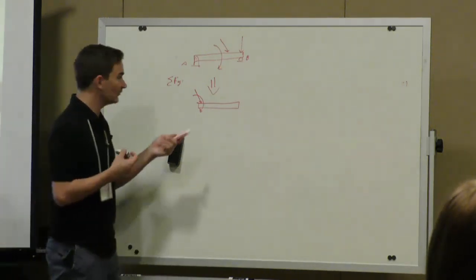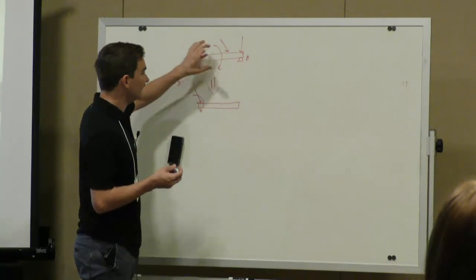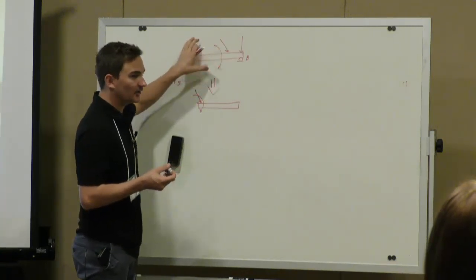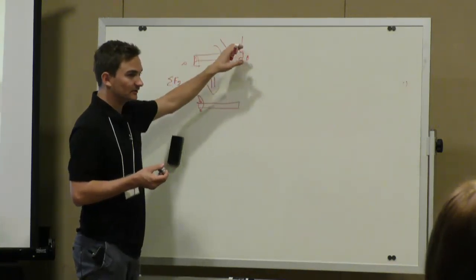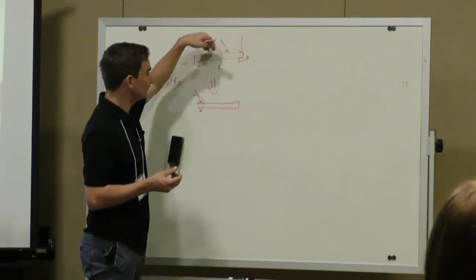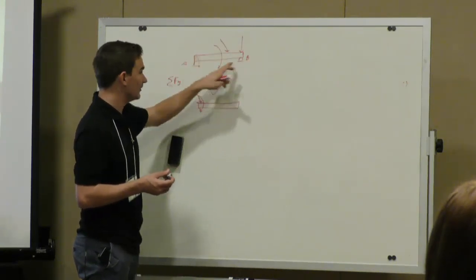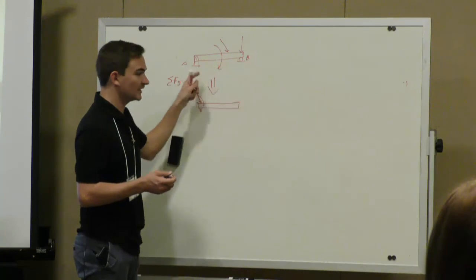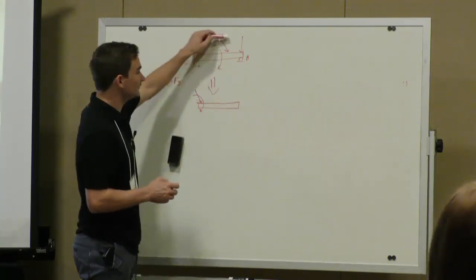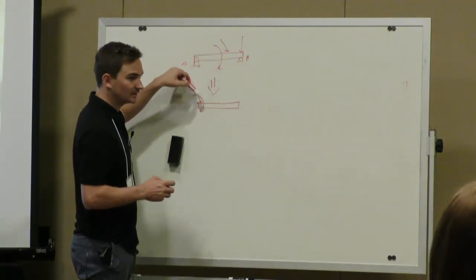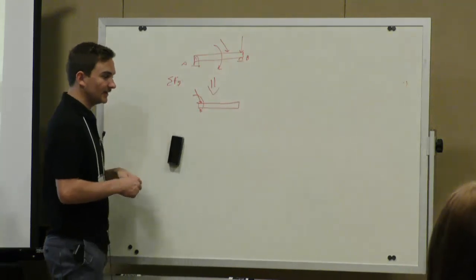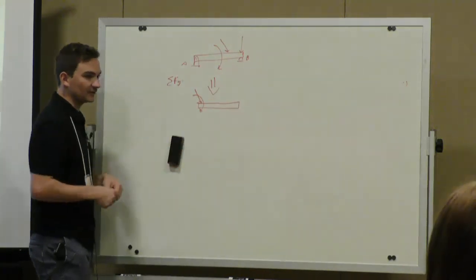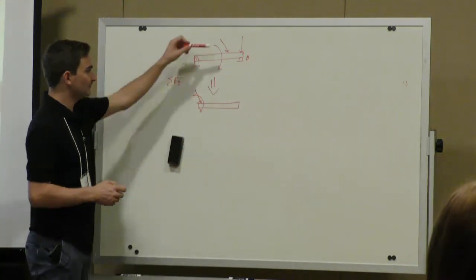Yeah, so for an equivalent system, you don't have to worry about the support reactions. You care about the external loads. So you care about this force and this moment. You don't worry about the reaction forces, because you want to convert these forces into just one force. So that's the purpose of it. And then you could solve for your support reactions after if the question needed. But for equivalent systems, you just try to simplify it.